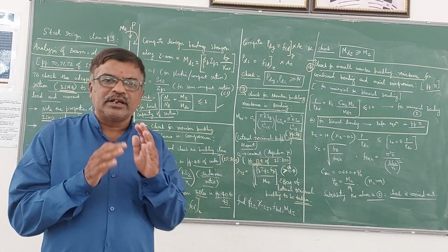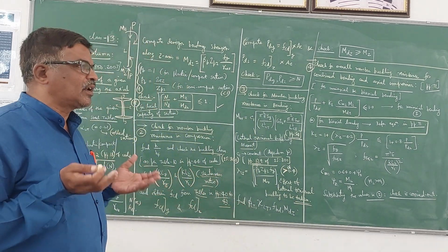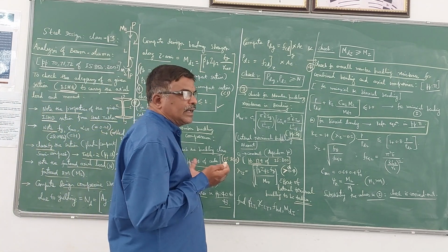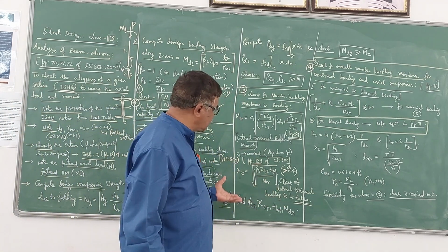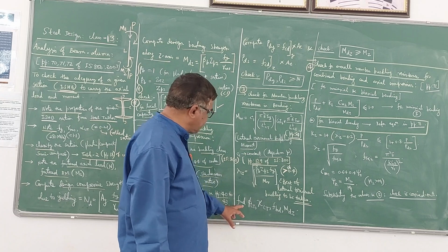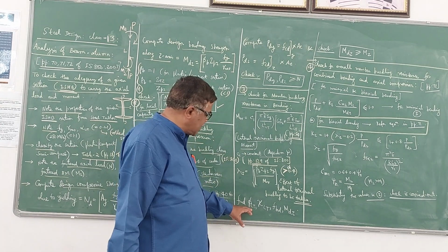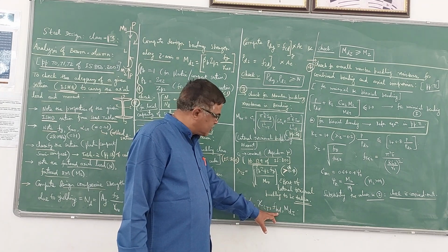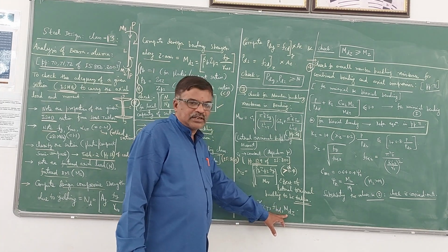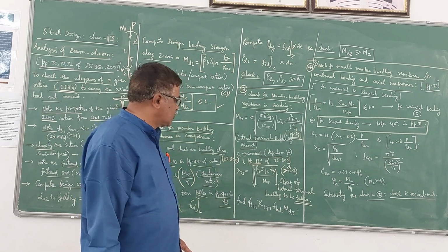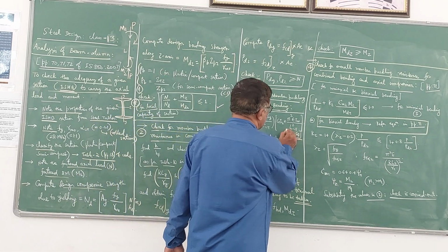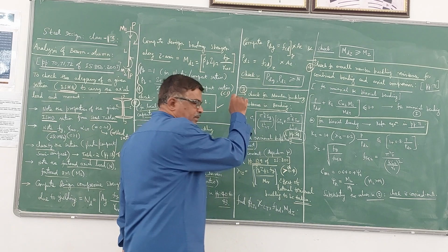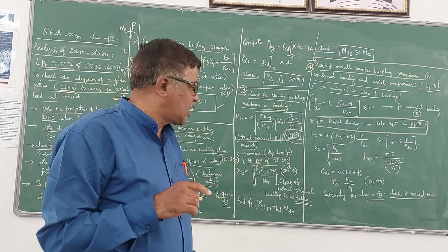The same procedure which we have used in the design or analysis of laterally unrestrained beams, same procedure we are following here. Then we have to calculate some more parameters, phi LT, chi LT, and design bending stress, and then MDZ, that is the design bending strength. All these are available on page 54 of the code. All the steps and equations are available there.